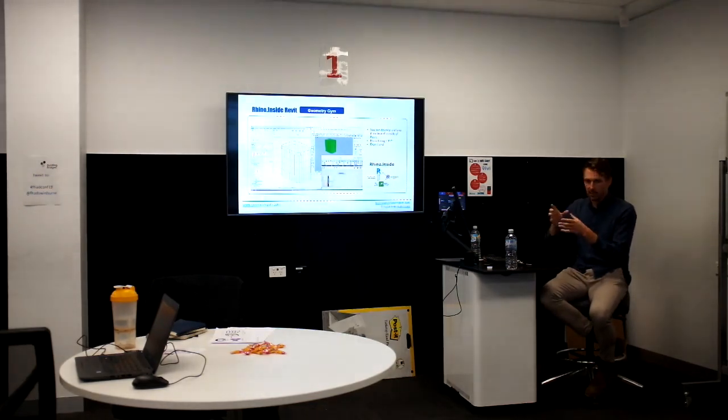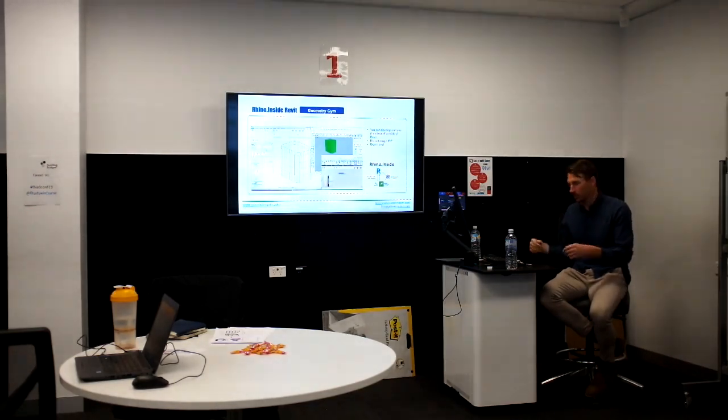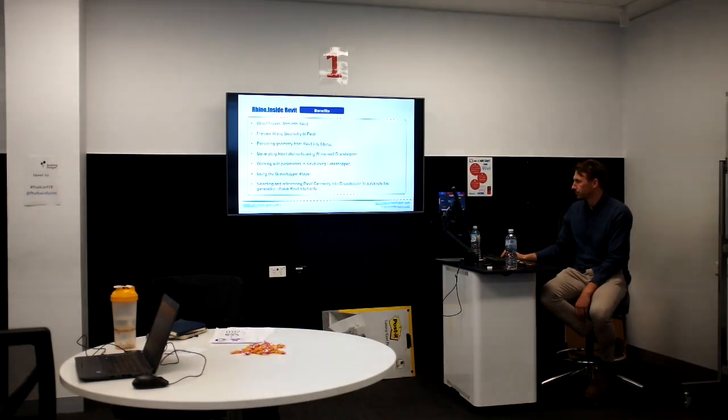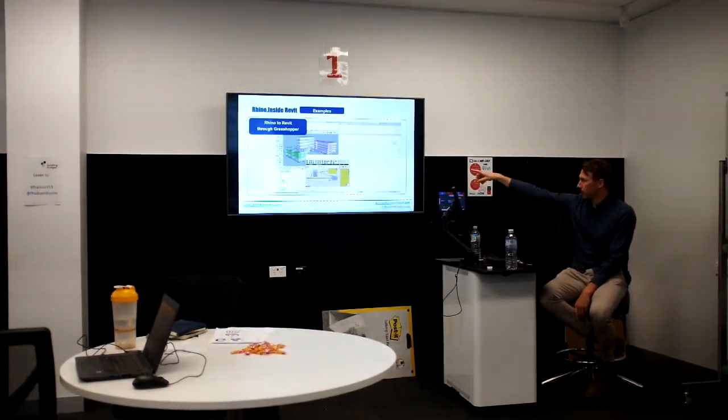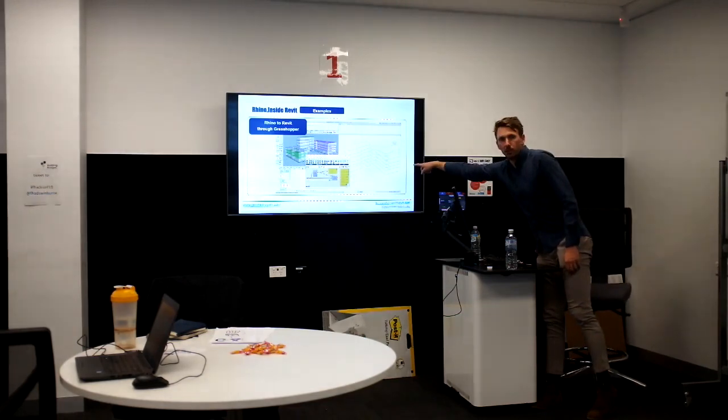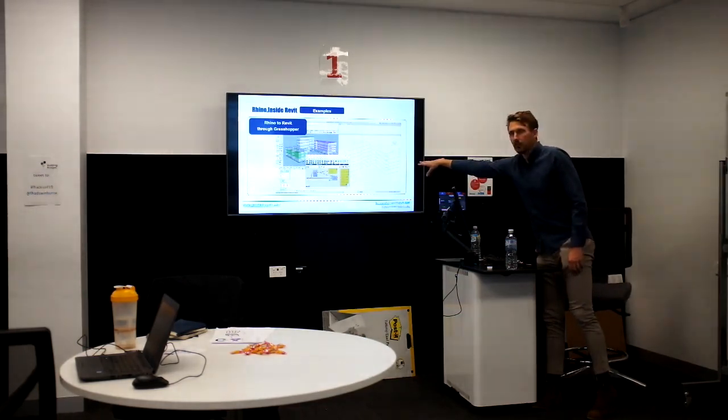Every time you make a change to your facade and re-bake it, it will check whether there's an element with that IFC GUID and update that element. So it won't lose the connection. I'm not 100% sure with the Rhino Inside stuff itself. If you look at this image, they've baked floor plates, so that's their Revit elements.